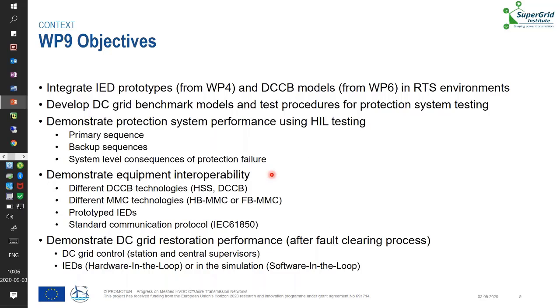One important point of the project is to demonstrate interoperability. For that, we use different kinds of models, different kinds of MMC technologies, prototyped IEDs for different components: converter relay, line relay, supervisor, and above all, we implement a complete communication architecture based on the IEC 61850 protocol.